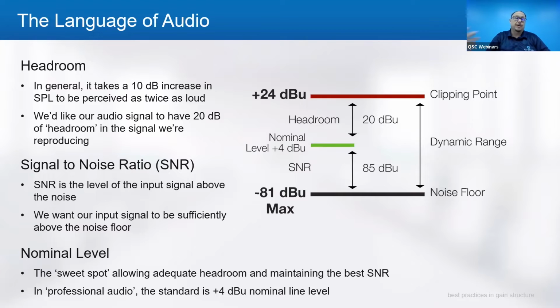That's why when you come in out of unbalanced outputs from a consumer device, you may have to give it some dB of gain to get it to that nominal level. Microphones, we typically say are around negative 60 dBV or negative 57.8 dBu, but there really is no standard microphone value. For condenser microphones, levels will vary quite frequently. So that will be microphone dependent, but a standard dynamic mic is about 60 dB down.